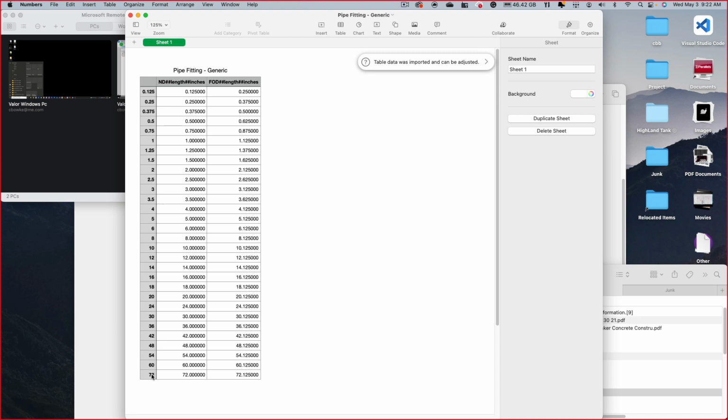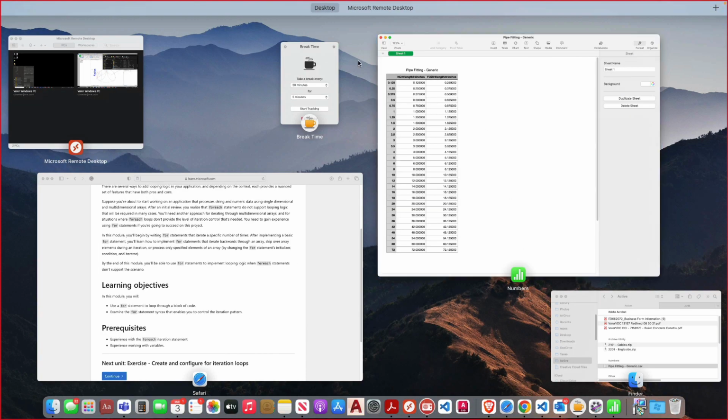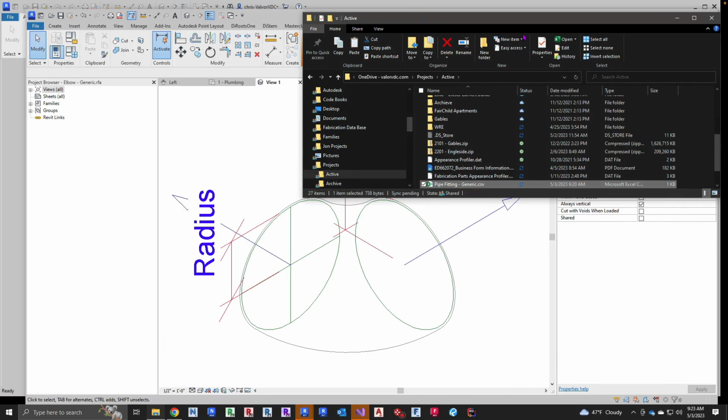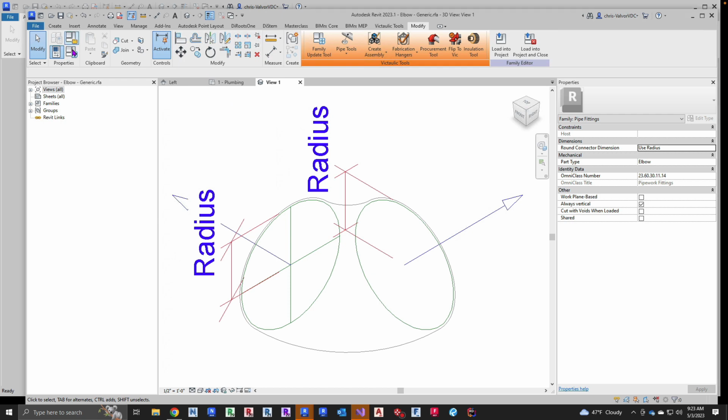The first column tells you basically the pipe size that this will go up to. If you're trying to run 96-inch pipe, it won't work, but you can take it all the way up to 72-inch. And all it's telling you is this is the diameter. And then this is the fitting outside diameter right here. So it's 1/4 inch for 1/2 inch is 5/8. So this is like copper sizes. And 1 inch is 1 1/8. And so this table here is referenced.